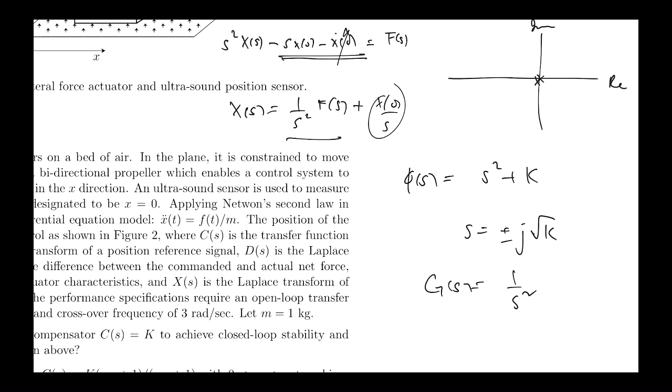We know that for small values of k, we'll end up with closed loop poles that are close to the open loop poles. But we have to satisfy the phase condition that defines the root locus. In order to satisfy the phase condition, the closed loop poles will be moving away from the open loop ones at angles of -90 and +90, and we go towards the zeros at infinity along the imaginary axis as we increase k.